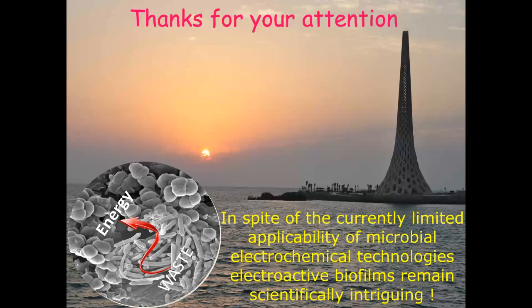Actually, we use chlorination before extracting the water. We pump chlorine so we can kill the pathogens, including viruses, before we extract the water. And second, whatever biomass is inside the reactor, we remove it frequently as part of the life cycle, and we collect it and dry it, and we can use that as fertilizer.